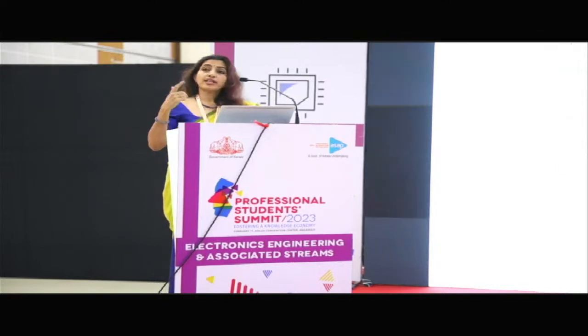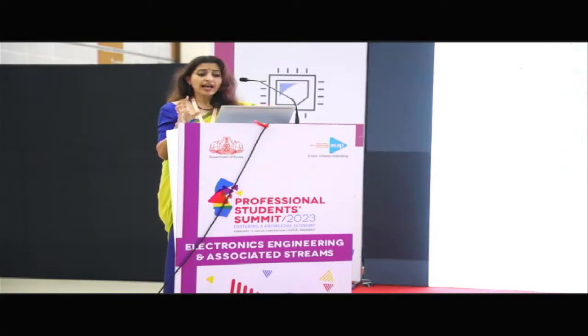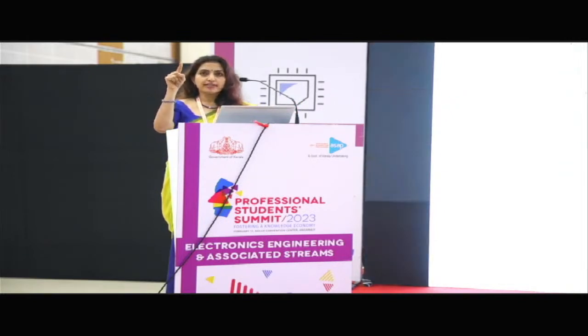And there will be an auto sequencer algorithm. It is not like you can switch on anode first, then cathode first, then heater first. There is a particular sequence for this operation of the SPT, and it is very, very crucial. So we have an auto sequencer algorithm which will be sitting inside the controller, controlling all these operations. Further, the control unit has a much more difficult task to control all the feed system elements which I have shown earlier in the correct order, so that the pressure in the tank, which is around 180 bar, will be available at the cathode and anode at around 2 bar. So all these systems should be operated in sequence, and that will be done by the controller.